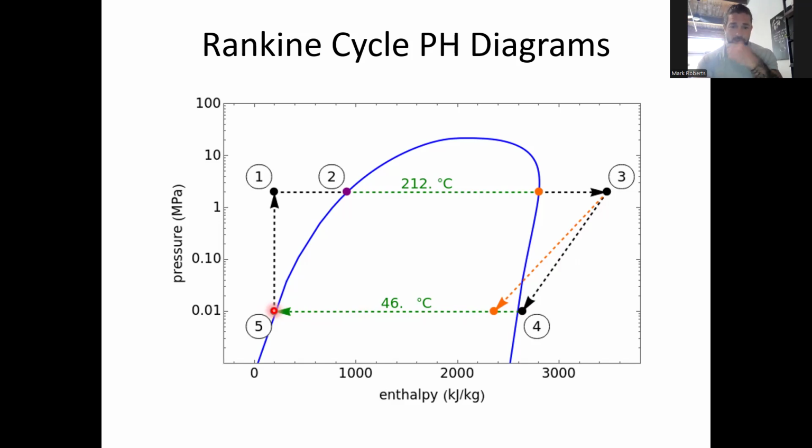And again, based on the change in pressure that we want, we can calculate the change in enthalpy required for that. So that's just going to be a V delta P, and we can look up the specific volume of water or fluid at those conditions. And this change in pressure might be a specified operational pressure that we want to operate our system. So we can work over whatever pressure that we want depending on instrument or systems limitations. Again, any higher pressure is typically better.